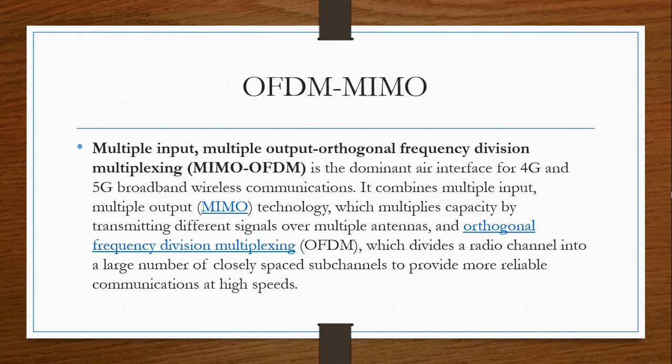Greg Rayleigh invented MIMO in 1996 when he showed that different data streams could be transmitted at the same time on the same frequency by taking advantage of the fact that signals transmitted into space bounce off objects such as the ground or buildings or any other obstacles and take multiple paths to the receiver. That is, by using multiple antennas and pre-coding the data, different data streams could be sent over different paths.